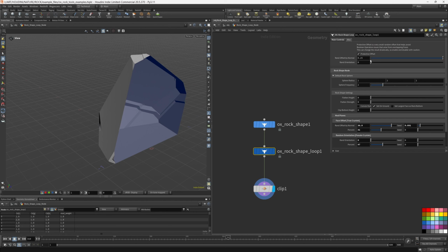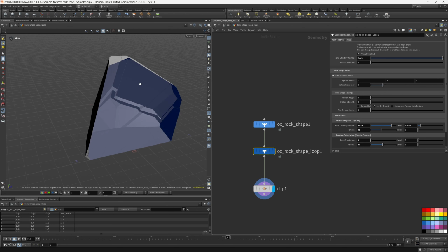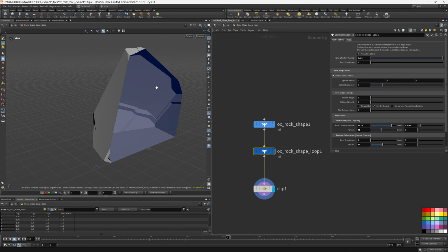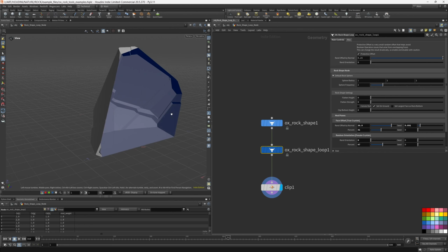It's just a very tiny, minuscule offset so that the planes don't intersect with each other, and the Boolean runs a lot faster. I don't know why that's how it works. It just works that way. I wish it didn't, but you can modify that a little bit here if you need to for any reason. But for most cases, just leave this on and you can ignore it.